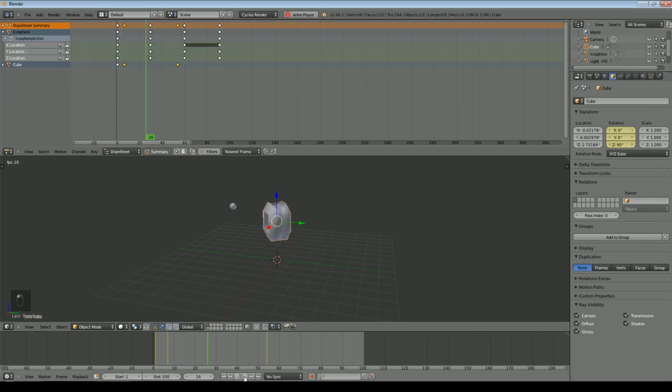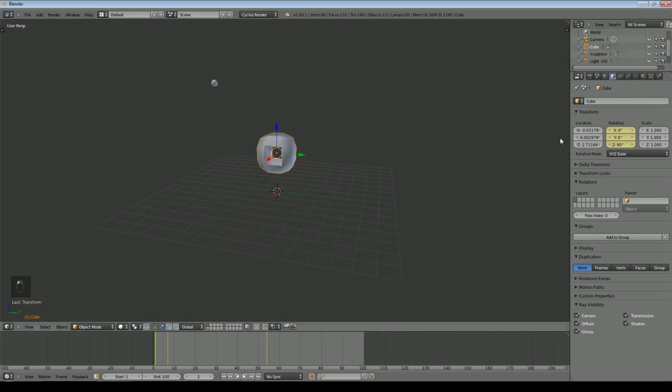So then we press play and you notice it's already trying to close by the time the ball comes through. So that's a quick way to move where the keyframes are, and as I said, you can see the keyframes represented here for the object you have selected. So if we close that now, you've got an animation and you want to render it.